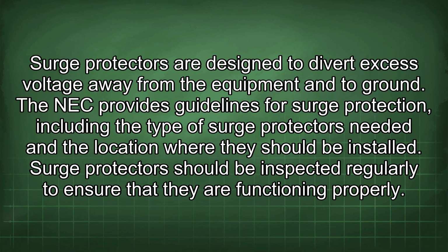Surge protectors are designed to divert excess voltage away from the equipment into ground. The NEC provides guidelines for surge protection, including the type of surge protectors needed and the location where they should be installed. Surge protectors should be inspected regularly to ensure that they are functioning properly.